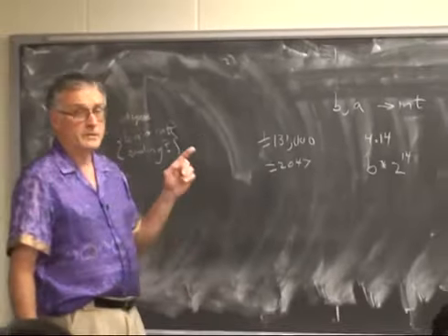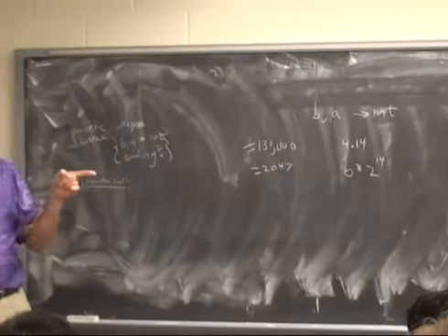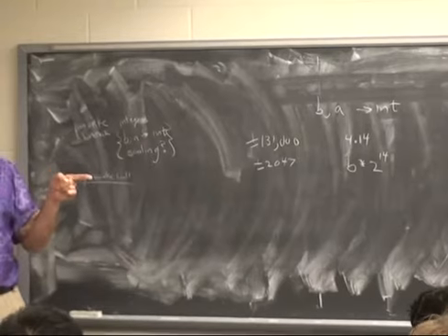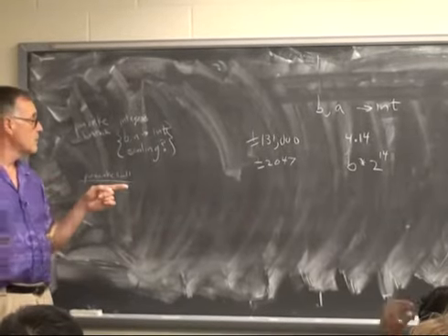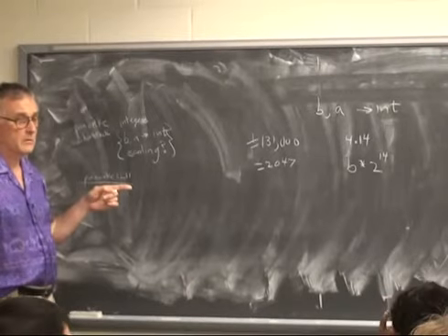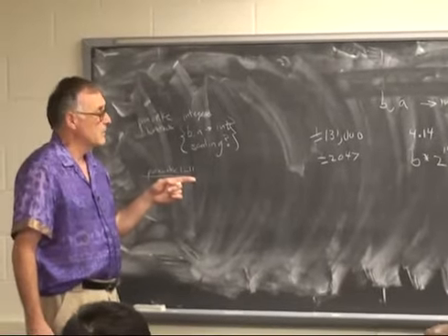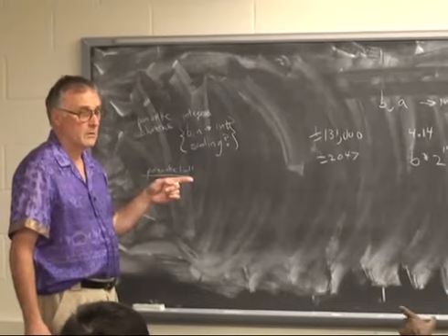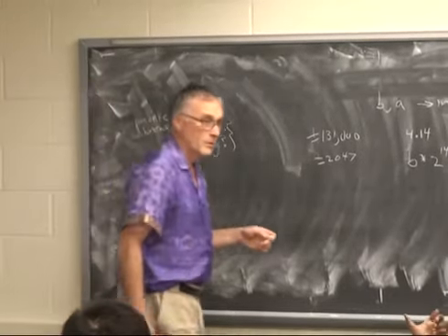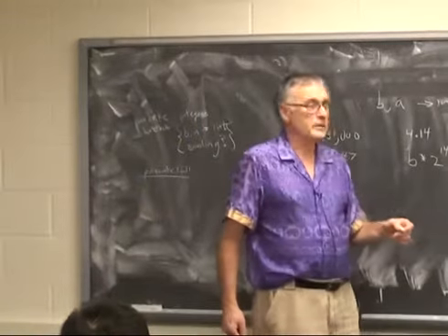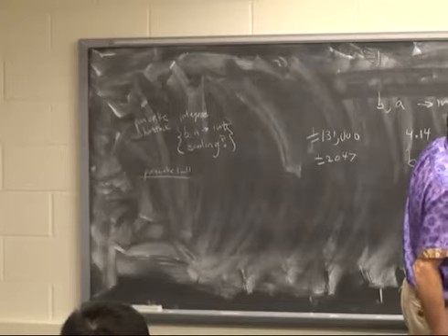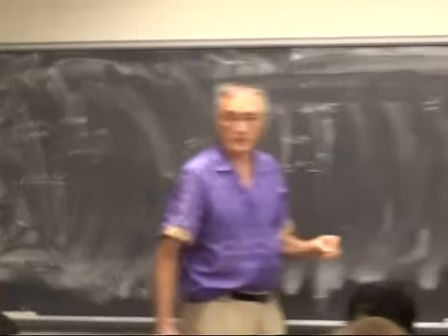The compiler does not recognize hexadecimal numbers, only decimal. Yeah, I get it for the coefficients, scaling the coefficients. What do you do for the audio signal which is coming as input, which is 16 bits? I mean, how do you treat that? Is it like a fraction? It is a fraction. Yeah, the 16-bit audio signal coming in is normalized to plus minus 1.